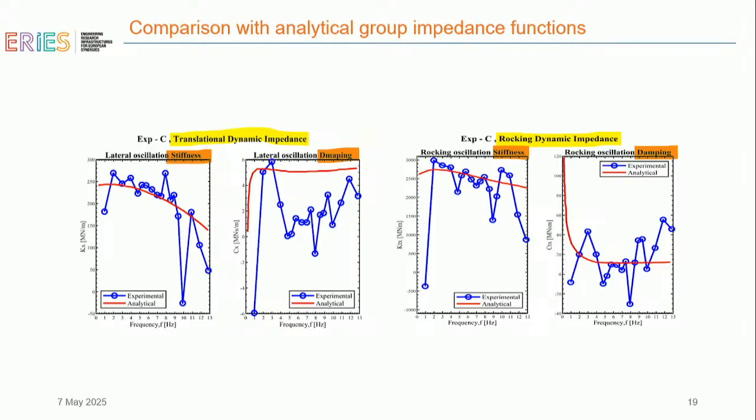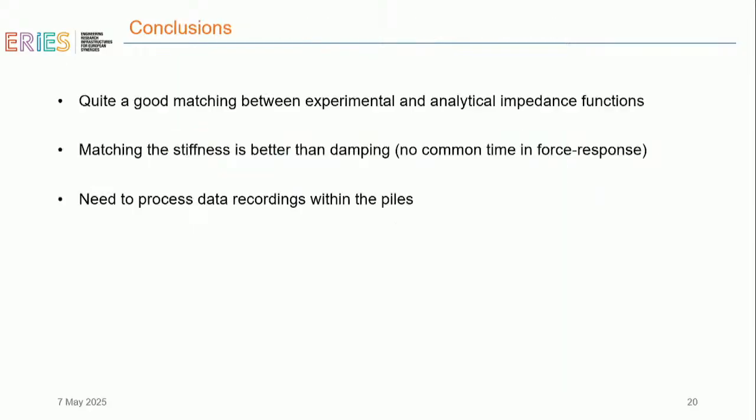The second problem is that our eccentric mass shaker does not connect to a GPS, because someone might say, why don't you connect everything to the GPS? The eccentric mass shaker does not connect to the GPS. So this is all from back calculation, and my estimate is that probably there is something like that involved in the estimation of the damping, and obviously we need to keep on working on this.